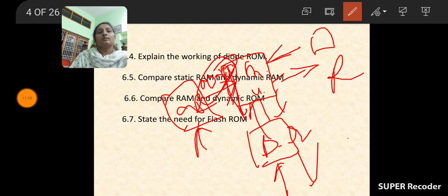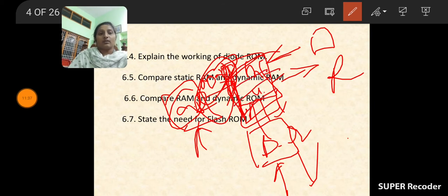With binary numbers only we can address the memory locations 0000, 0001, 0010, 0100. If we are able to give the address of a memory location in a particular register, it is easy to access that particular location. So the address register is used to store the address of different memory locations. And the buffer register is used to enter data into the memory or to receive data from the memory.